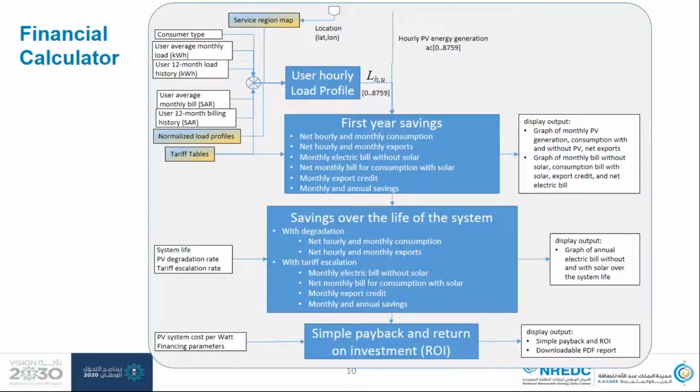of load profiles for different customer classes throughout the kingdom from SEC. They did a study that collected data on something like 2,500 meters, geographically distributed through the kingdom. And so we are using that to provide a standardized load profile for any customer based on what their monthly consumption is. We can scale that hourly load profile to match their monthly consumption pattern, but it will provide the daily, or the hourly consumption pattern that is consistent with sort of a median case of the different user classes.